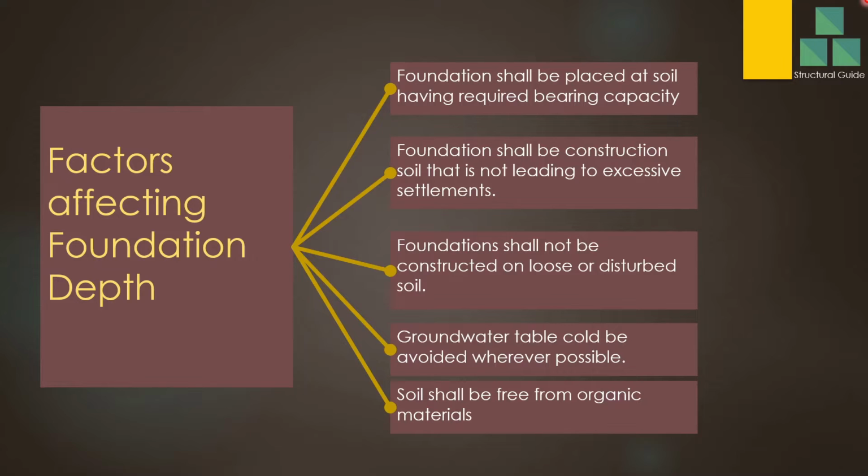This basically comes from the geotechnical investigation. If you have done a geotechnical investigation, you can obtain this data through the boreholes. The borehole clearly indicates the type of soil available under the ground. Based on that, you may get the recommendation and follow it. In addition, you should have the knowledge to see whether these recommendations are correct or wrong. With that, you can determine the foundation depth, and whether we can go with a shallow foundation or whether we require a deep foundation. All those can be determined from that.